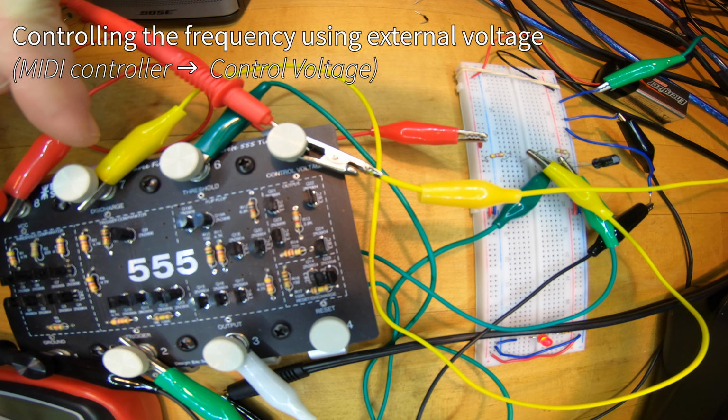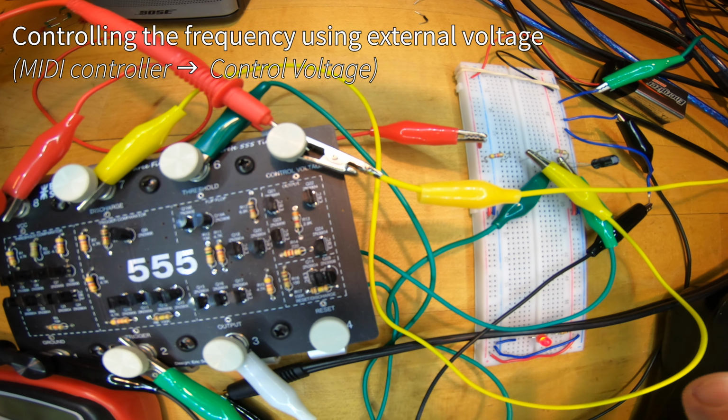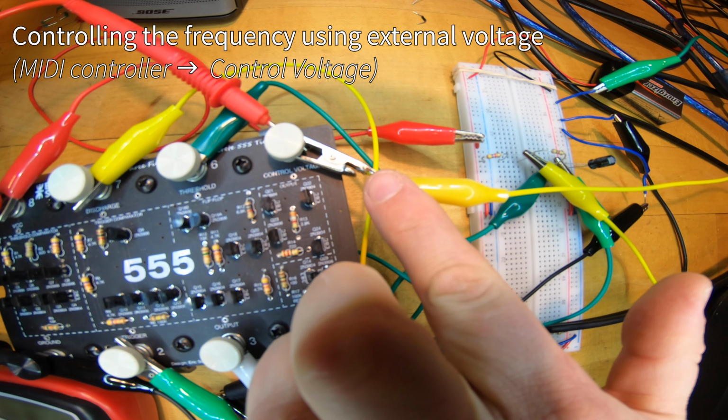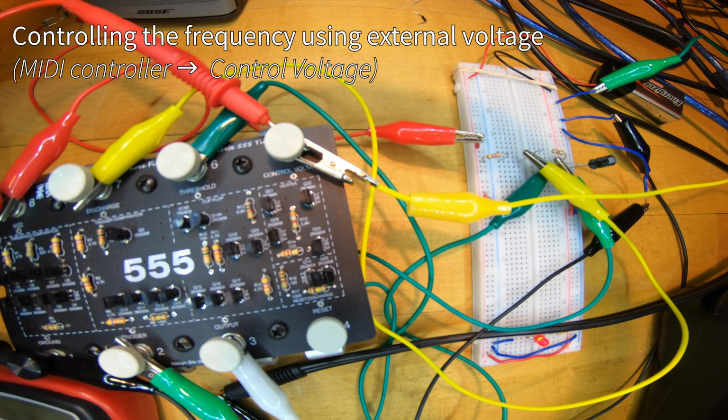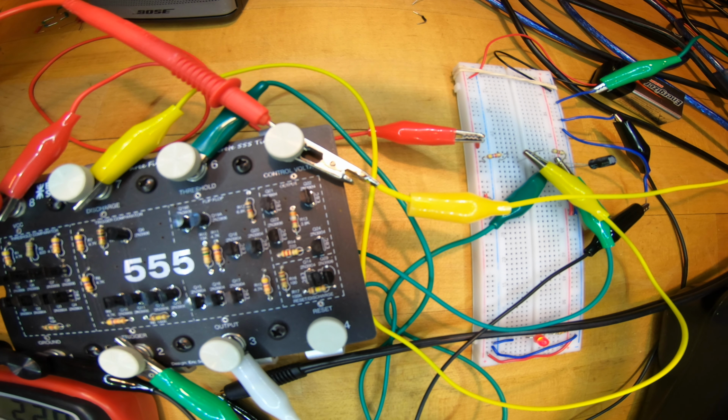So here's another more exciting final example of controlling frequency. In this case, I'm going to use a MIDI keyboard that goes to a CV or control voltage converter and actually bring that into the control voltage. So now I have an external piece of equipment which is controlling my 555 timer.